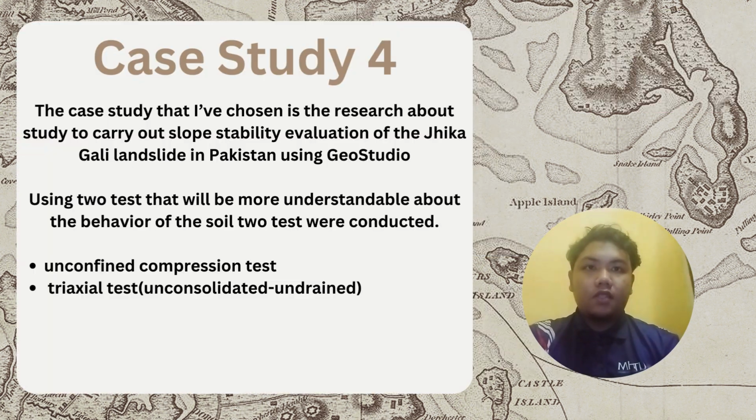Assalamualaikum, my name is Muhammad Aziz Zikri. The case study that I've chosen is the research on a slope stability evaluation of the Jika Gali landslide in Pakistan using GeoStudio. To better understand the behavior of the soil, two tests were conducted: first the unconfined compression test and second the triaxial test, with more focus on the unconsolidated undrained triaxial test.